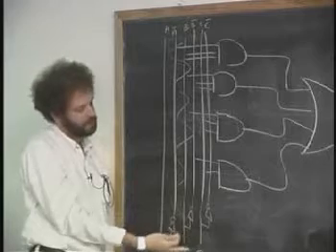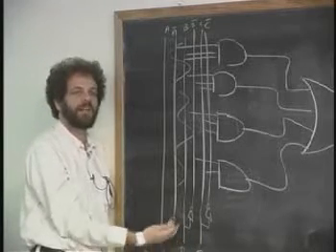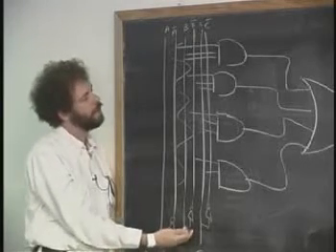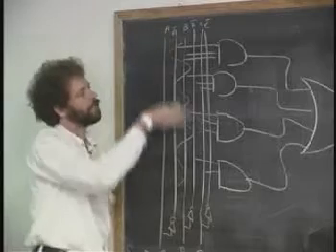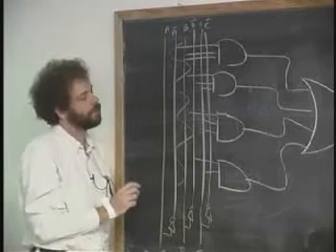Okay, so the first thing I'm going to do is take all the inputs and form their complements, the NOTs of them. And then I'm going to have this matrix where I can hook up some wires to each other.